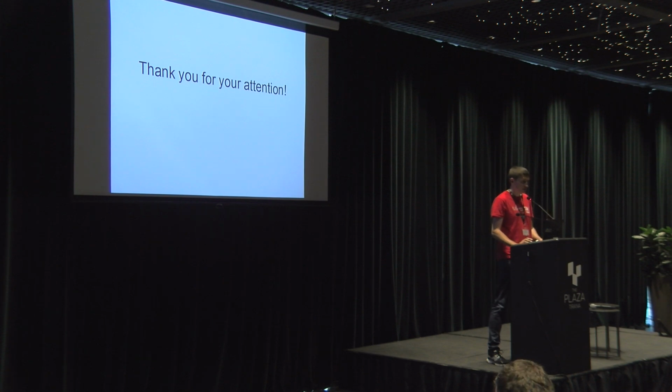So would we expect a complete loss of signal between the link? It depends on the intensity. If it is heavy rain and you can't see the other side of the link, most likely it will get disconnected, because the transmit power is limited, and most of the gain is achieved with the antenna.